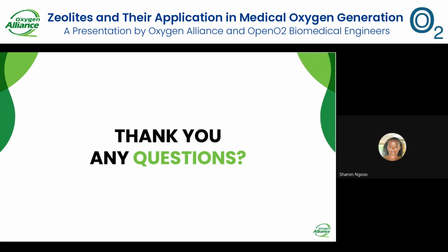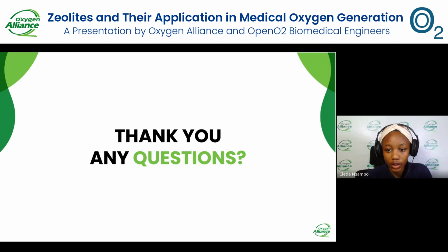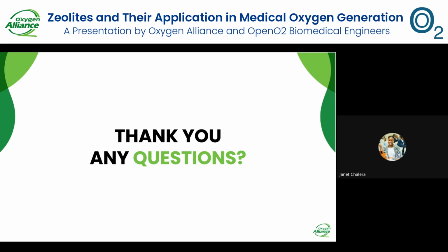Thank you. Janet, they've clarified that by colon they mean the sieve bed tank. I don't know if you want to add anything to what you answered earlier. What I would add is that the replacement of the whole colon, as you're putting it, or the sieve bed tank, is more expensive than just refilling the zeolite. So you have those two options, and you can weigh your options.